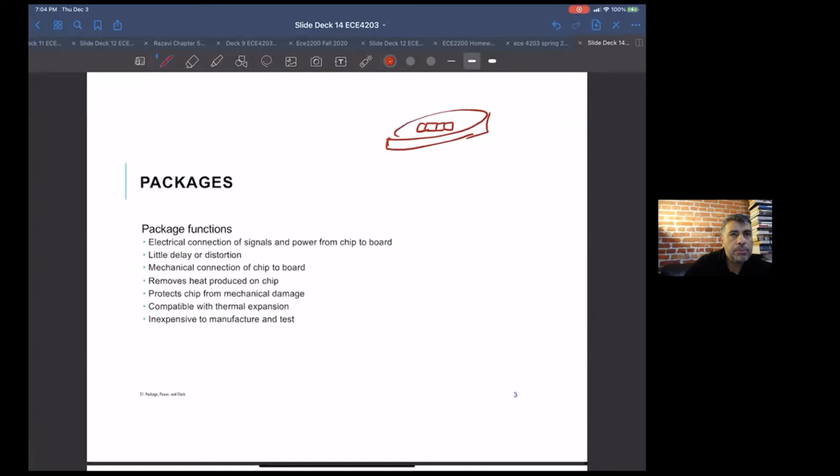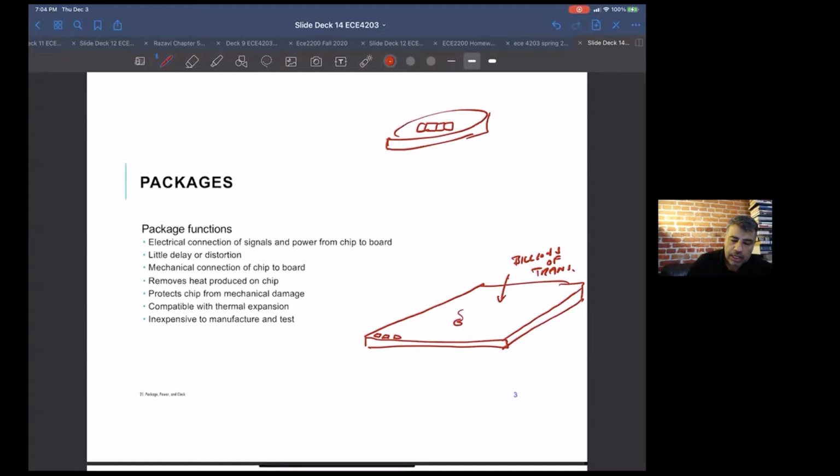So you need some technique to connect up to these chips. And these chips need to be rigid mechanically. Basically, it's like a mechanical and thermal interface to the rest of the system. So let's say if I just look at a chip, let me actually draw it super big. It'll be a piece of silicon. It's always square because that's how you dice this thing. And it has, I don't know, billions of transistors in it. You have all of your circuits here, and the stuff's getting distributed in these metal lines, etc. Wherever you had outputs, you have these pads, which are just openings.